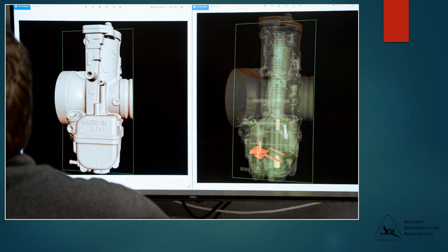This is a good example of how you can take a solid component, extract a 3D model from the CT, and use that mesh for FEA. We've also 3D printed some of these, in fact this component specifically, for exhibits or just for fun. You can isolate some of those internal components if you wanted to model them or measure any dimensions off of them.